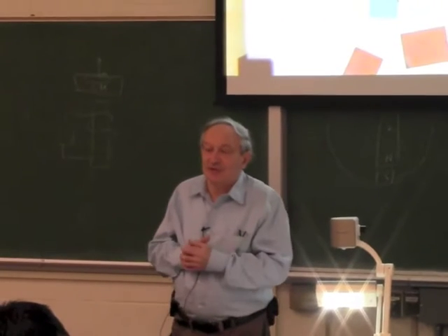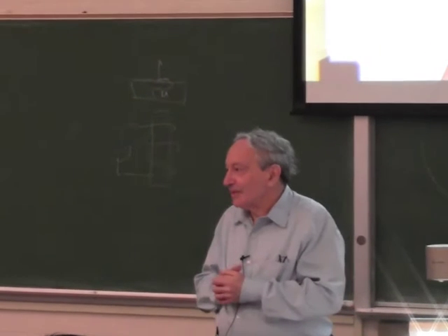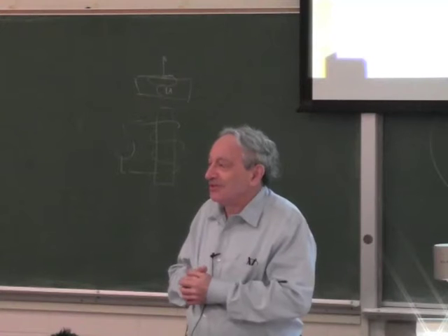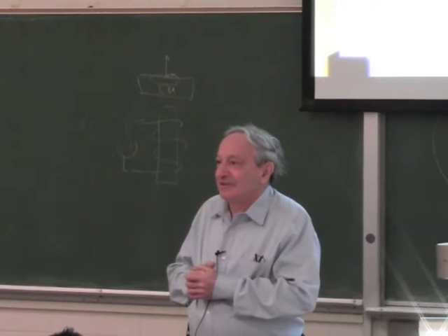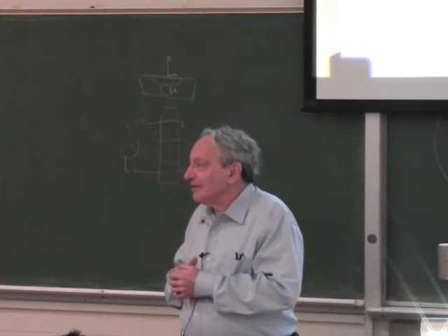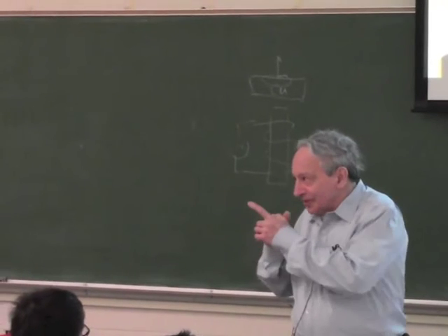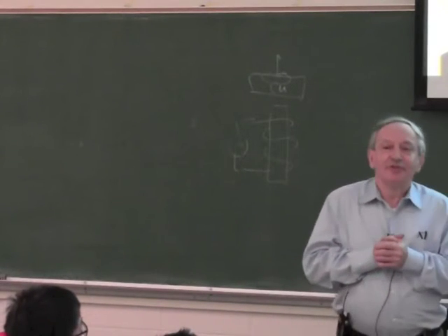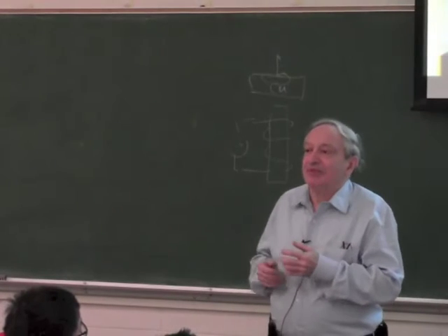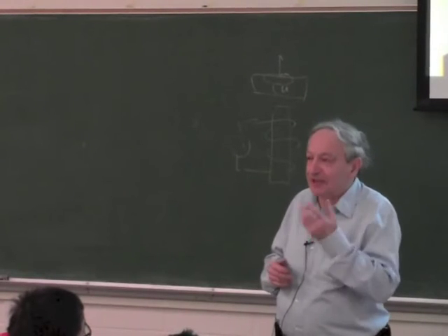Because all three are subject to Lenz's law. Steel is a ferrite material. Steel is what? It's a ferrite material. But it's Lenz's law, there's a current induced in it. Yes? Minimizing the reluctance, because it's a magnetic material, that opposes Lenz's law, I think. I guess it's two competing effects. Very good. There are two competing effects. If the material is ferromagnetic, there are two competing forces. Lenz's law tries to repel it, but since it's magnetic, the magnetic field tries to attract it in order to minimize reluctance or maximize inductance.